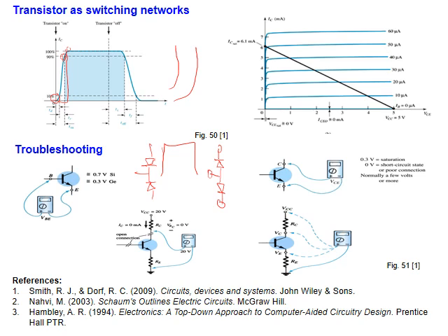For example, if I measure here and here, this is usually the voltage across the base emitter, 0.7 for silicon, germanium 0.3, but most transistors available today are silicon based. If I measure between collector and emitter, it is supposed to be 0. It is like measuring a diode: we have short circuit in one direction and open circuit in the opposite direction. The same thing here, short circuit in this direction, open circuit in the opposite direction. Between these 2 points there is open circuit all the time.